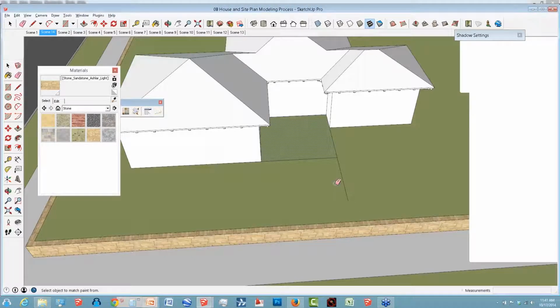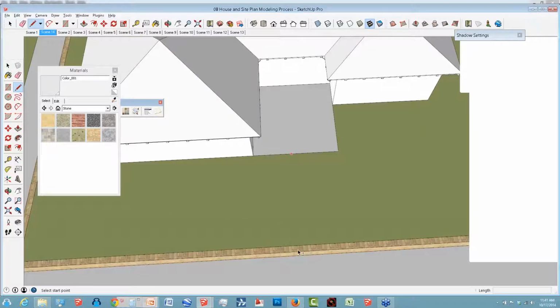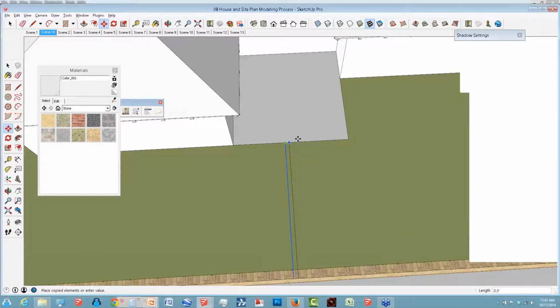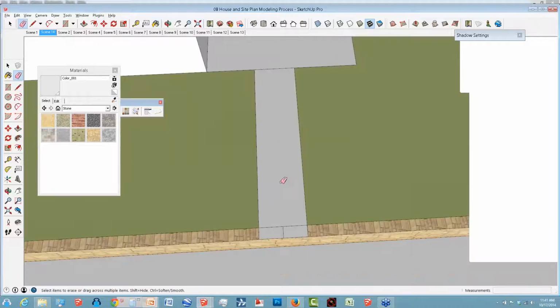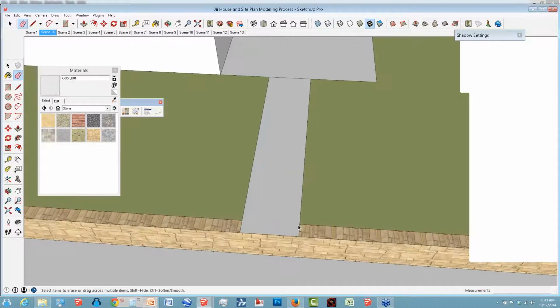And next I can continue to add lines. And the way that you can draft in SketchUp fairly effectively here, and I didn't go over something called the inference system because we don't have enough time, but what I'm using is the move tool to copy and move edges. I'm going to add my color to this as well. Wait for it to catch up. You'll see that I just created a surface, so I'm drafting on the extruded surfaces, not very hard to do, on the wall.